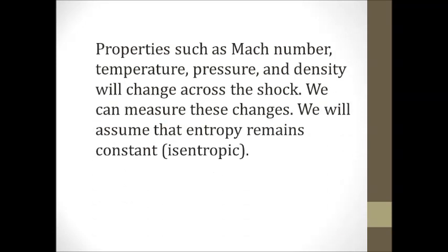Properties such as Mach number, temperature, pressure, and density will change across a bow shock. We can measure these changes. For this lab, we will assume that the entropy remains constant across a bow shock.